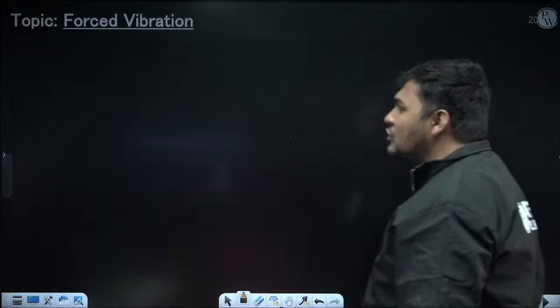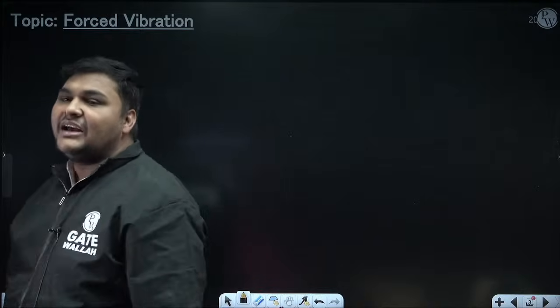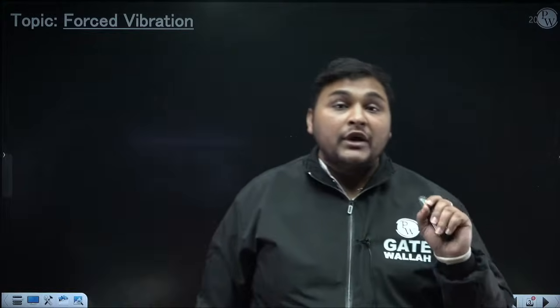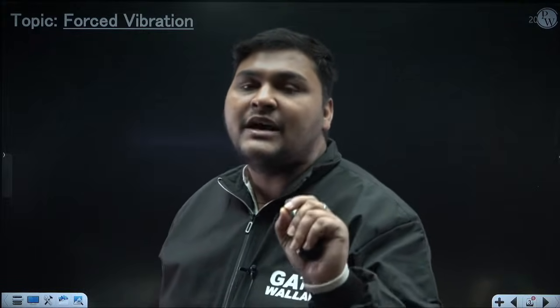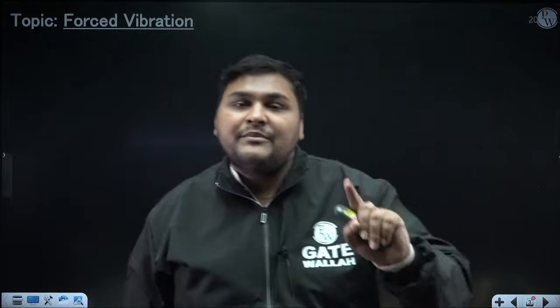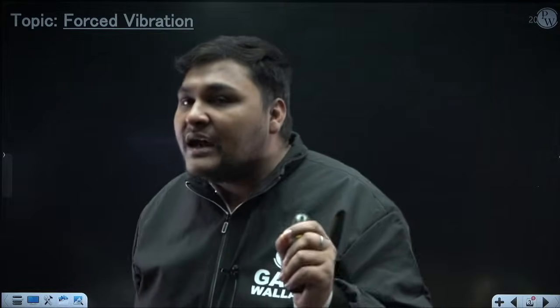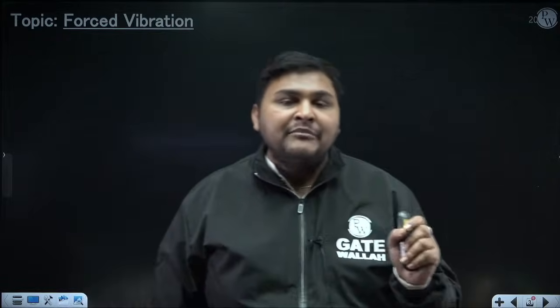First of all, what is forced vibration? In the last class we discussed free vibration, whether free undamped or free damped. But what is the meaning of free vibration? If during vibration no external time dependent force or disturbance acts in the direction of vibration, then that vibration is free vibration. So for forced vibration, the definition is: if a time dependent disturbance or force acts in the direction of vibration, then that vibration is known as forced vibration.